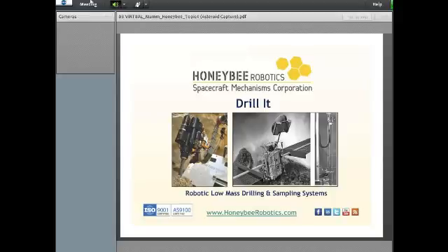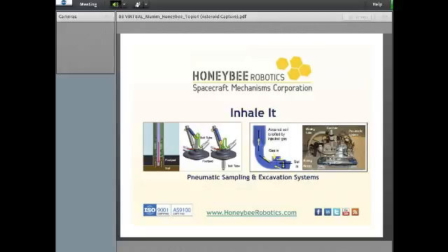And so this is, again, another method for performing some in-situ science, for collecting a sample from the asteroid and characterizing it. And then we've also developed some pretty novel pneumatic sampling systems. So this could be used for very low impact systems where you essentially use pressurized gas in a way similar to what Brian was alluding to earlier in this morning's discussion. And it actually takes very, very little gas to acquire a good amount of loose sample.